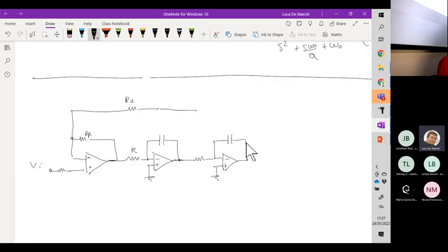The second integrator output is provided to the macro feedback loop, while the first integrator output is given here in this conditional feedback loop, which is indeed a quite critical one, because the feedback is at the positive input of the op-amp.